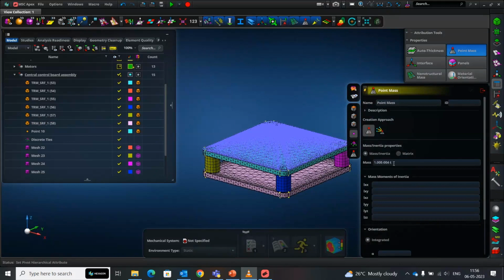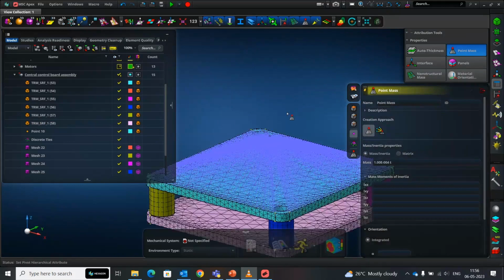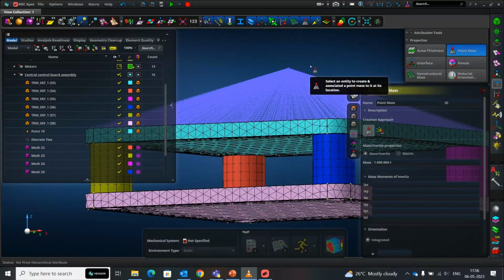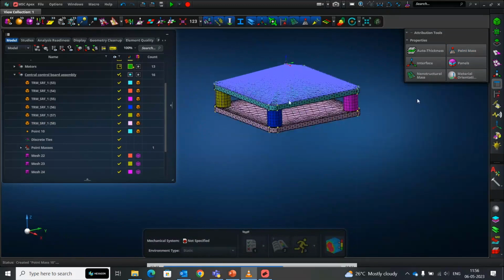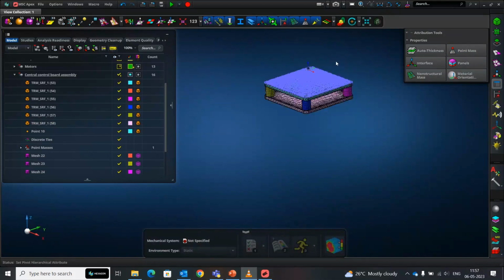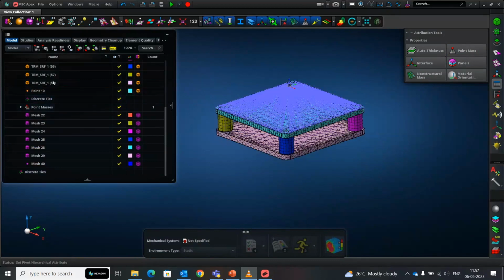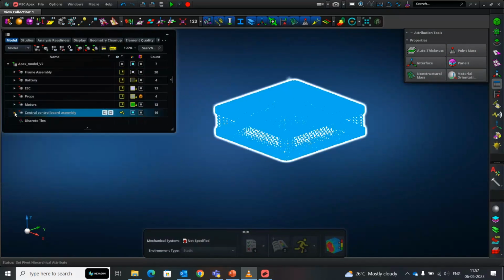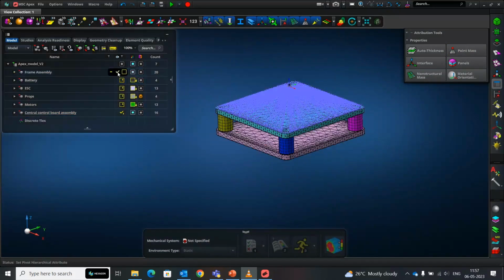So please note, again, like I mentioned, you can also incorporate the mass moment of inertia. It is more appreciated to be present, especially when you're doing dynamic analysis. So please do go ahead, evaluate the mass moment of inertia. You can place the IXX, IYY, and so on and so forth. So once you're done, okay, now pretty much all of these have been assigned.